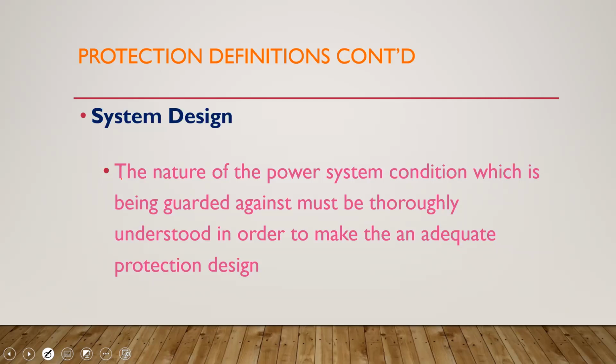One classic protection system that we utilize is that of an earthing transformer. Now, where do I use this? Why do I use it? If you understand that for your generator, you're going to be earthing the windings, it's a star winding earth.